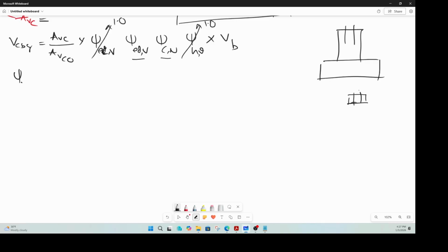So let's start with CED comma V. Again, this is edge distance related modification factor, usually a function of what your CA1 and CA2 are, right? In this case, CA2 is 8.0 and 1.5 times CA1 is 14.25.